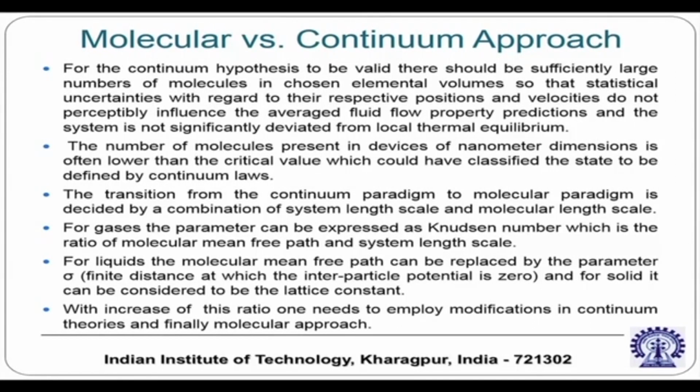So, to answer the question whether molecular modeling or continuum modeling will work, one has to look into the continuum hypothesis, that there should be a sufficiently large number of molecules in the chosen elemental volumes, so that uncertainties with regard to their respective positions and velocities do not result in any appreciable deviation in the prediction of flow properties and fluid properties.